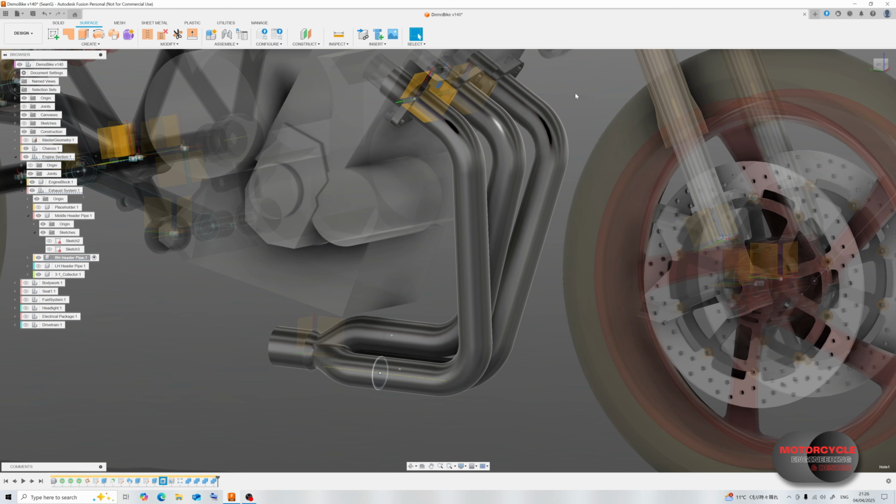So usually what you're going to see is some long sweeping bends in the exhaust, and the reason for that is, one, packaging. It needs you to do that in order for it to fit, but the main point is actually for friction loss. So if you have a very sharp bend in your pipe, you can have a much greater friction loss than if you have a long sweeping bend. That sharp bend is going to be worse in the long run.